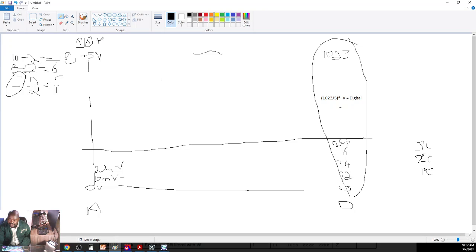Add that, there's another one. The results are 4. Go back to the loop. So we are going to get this as our quotient depending on how many times we successfully subtract 2 from this ADC result. That's what the loop has to achieve. And this will actually be our temperature.